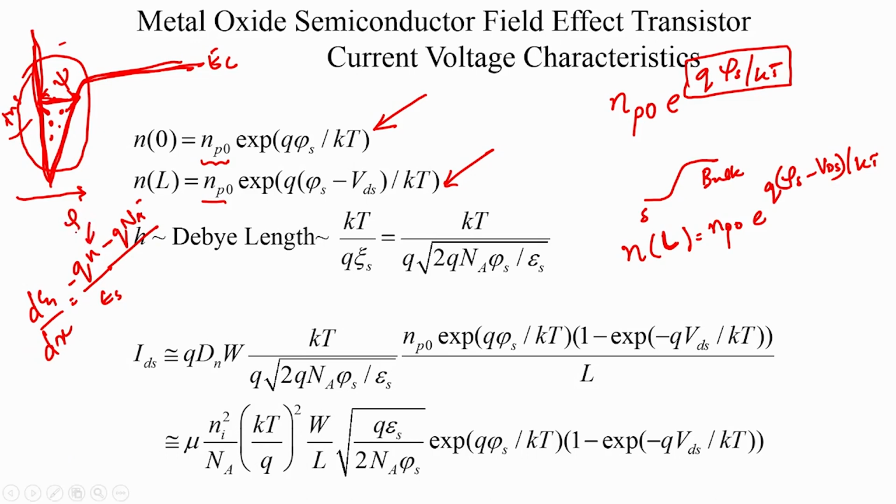We have already looked at this case when we looked at the ohmic metal semiconductor contacts. If you remember the ohmic metal semiconductor junction, of course, there we probably used an N type semiconductor in the analysis, but nevertheless the idea is the same, and you do have an electron charge which is dependent on the potential, and therefore, you need to use those techniques to solve Poisson's equation.